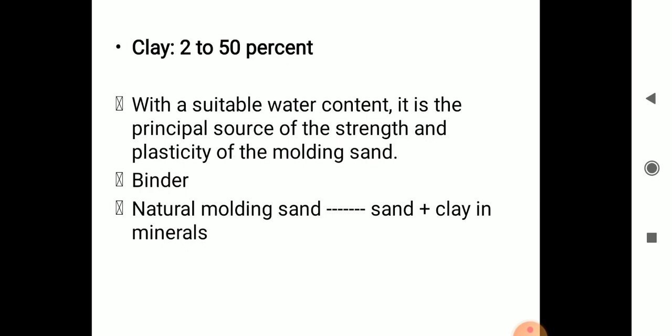Synthetic molding sand is essentially an aggregate of extremely small minerals of crystalline, usually flake-shaped particles that can be classified on the basis of their structure and composition into a few groups known as the clay minerals. Single clay mineral, mixtures of clay minerals, bentonite, fire clay and special clays are used as clay.